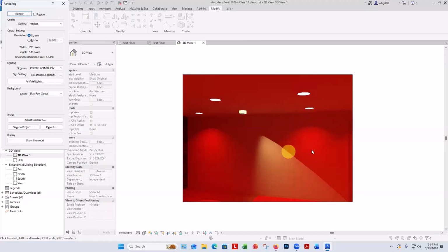And what's hard here is we have what looks like a white instrument giving us a red beam. And that's because what's in here, in this one, is a disk of glowing white material that Revit provides as sort of a cheat to make lights look like they're on, even if no actual light is hitting the inside of the housing. Easy to make and easy to edit family, but it's really not behaving the way families actually do. It's like close enough for Revit work.